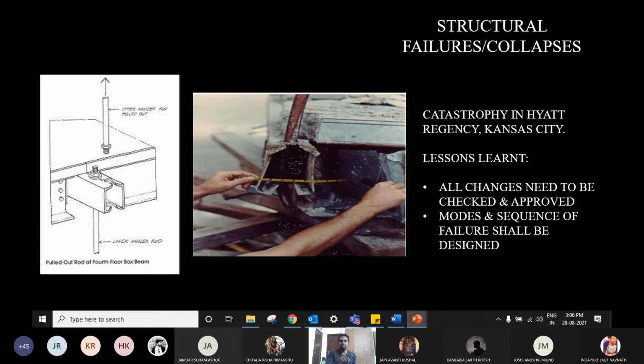And you find the load path, what happens? And you size your members and connections in such a way that your steel starts yielding, and you have a warning or indication, because steel is not going to snap off immediately, right? If it's going to yield, it's going to take some time, and there's sufficient warning. You can see visually, okay, it is being stressed so much, and there's a deformation happening. That's what we call a ductile failure.